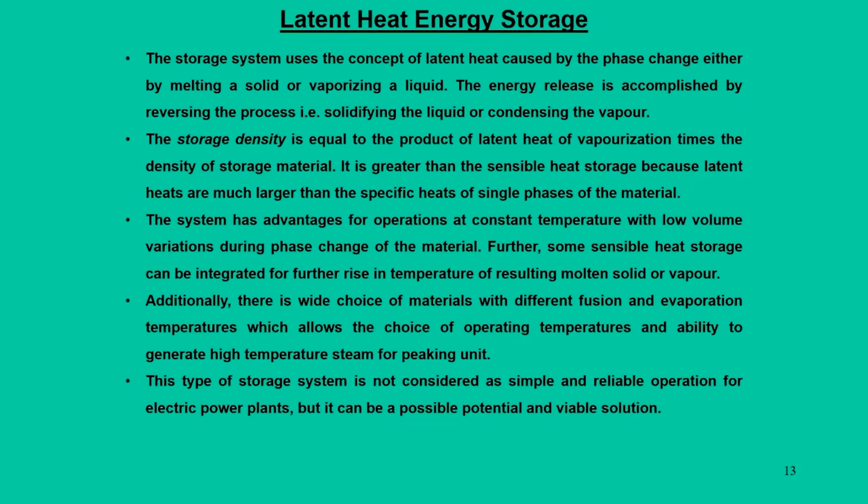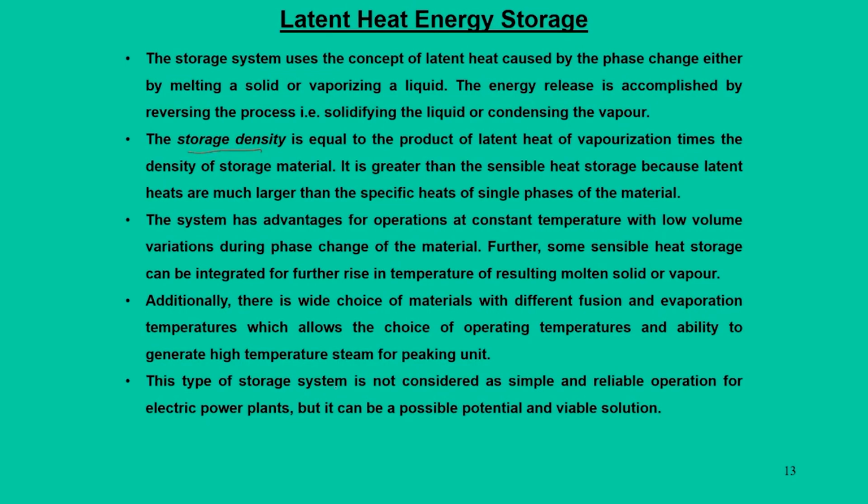Now, next we are going to move to latent heat based energy storage systems. When you say sensible heat storage, it is basically the temperature difference that plays a role. But when you talk about latent heat, there is no change in temperature, and we can think of phase change materials that are continuously vaporized and continuously condensed. Through this process we can store a substantial amount of energy, and here also we talk about storage density, which is equal to the product of latent heat of vaporization and the density of the storage material.